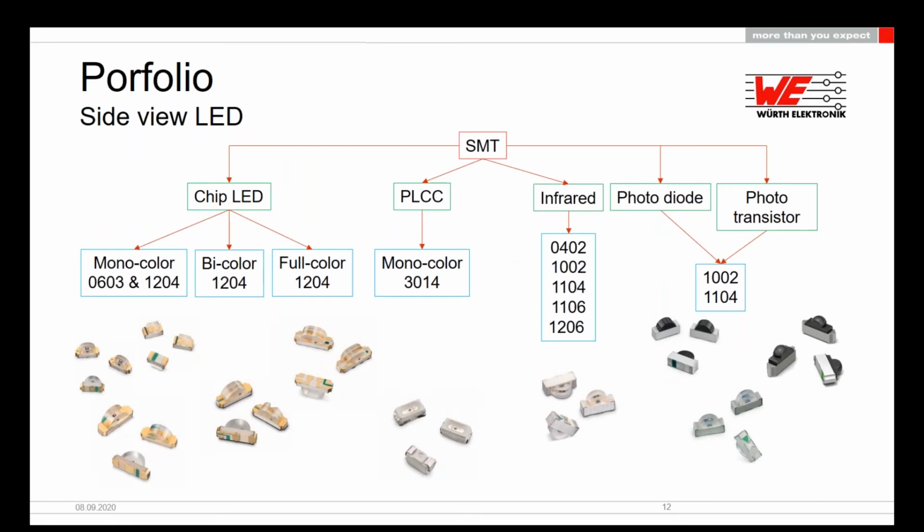Via the side view LED portfolio from Würth Elektronik, we provide the side view LED only in SMT. For the visible light, we offer the side view LED in chiplet package and PLCC package. We have also the side view package for the IR infrared light and photo detectors. Today our topic is about the visible side view LED. So please visit our webinar for infrared application to experience more about the IR LED and photo detectors.